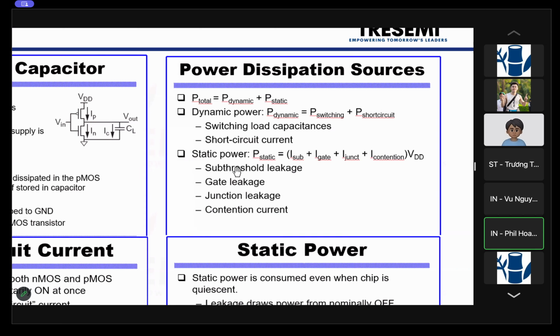So the challenge in designing an SoC for cellular phone and wireless applications is not speed, but static power. And as you go to more advanced technologies, the leakage becomes exponentially higher, and managing leakage is very, very difficult.